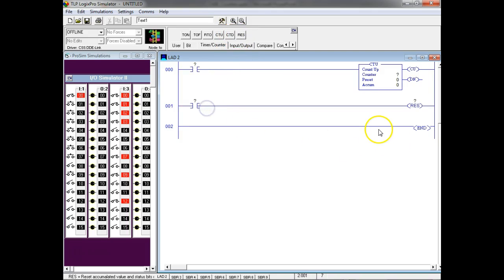Well, I see people use coils for reset, right? So we'll call this count. Oops, I'm sorry. Input colon zeros. No, I'm sorry. 1/0. I keep forgetting which PLC I'm on. Okay. Then we'll reset it with input colon 1/1. Okay. And we'll change these to push buttons.